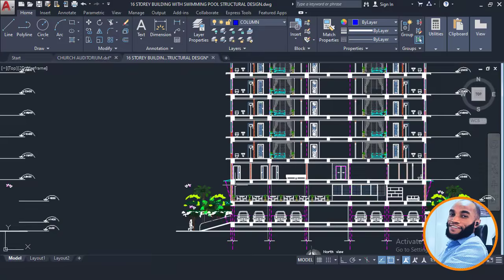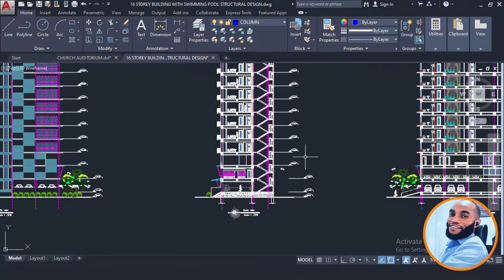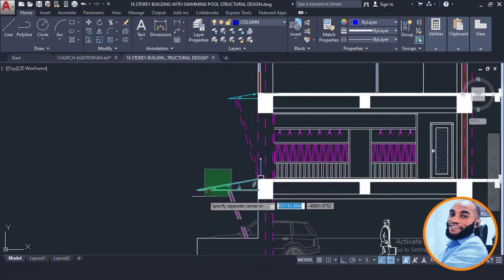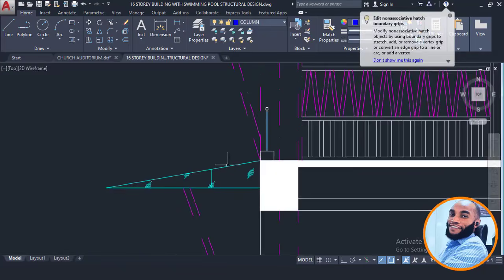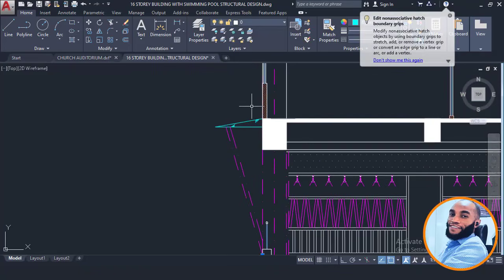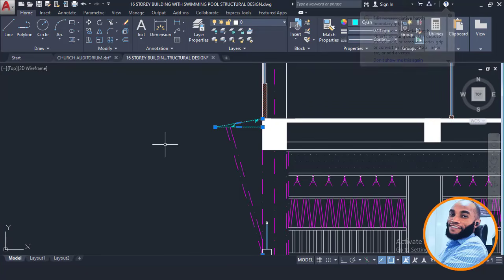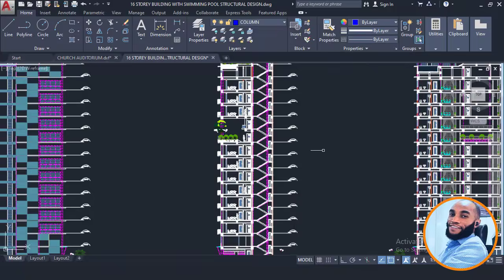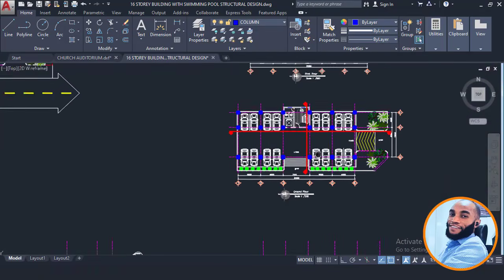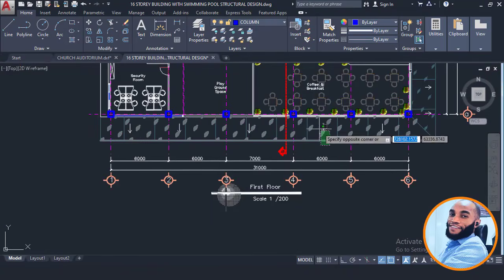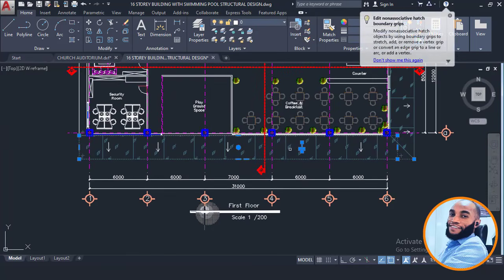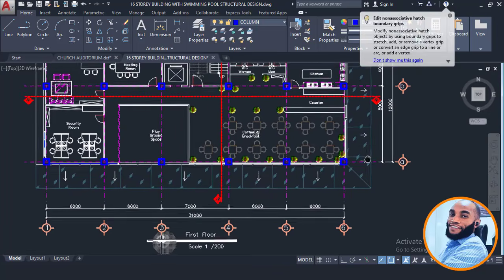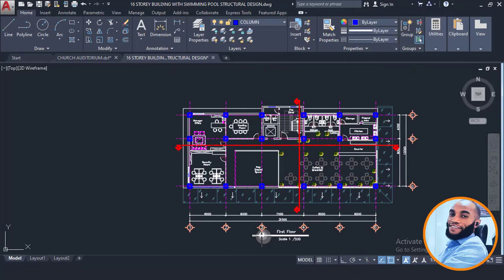What is that? On this place, this tells me that this is basically the canopy here. I can see that they have the same symbol. So this is a canopy, which can be either a plastic canopy and so on. Knowing that this is a canopy, I can choose to remove it from my structural modeling. So I will not consider this when I'm trying to model my structure, because this can have an independent member that carries it separately. Okay, now again I'll ask, what is the next thing here?